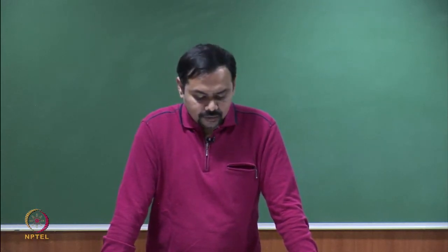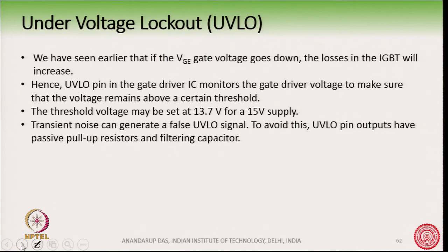But remember there may be a transient noise sometimes causing a false UVLO signal. So, generally these UVLO pin outputs have passive pull up resistors and filtering capacitors to get rid of the transient noise and a false UVLO signal.